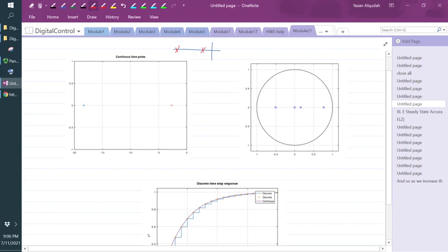These two poles resulted in two poles in the discrete time that are along the real axis. So in the previous case, a second order system results in complex poles within the unit circle. In the overdamped case, it resulted in two poles along the real axis.